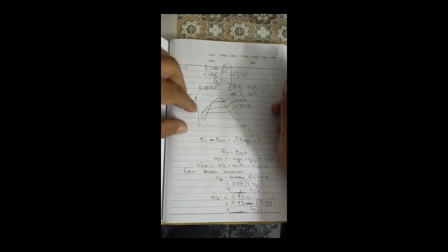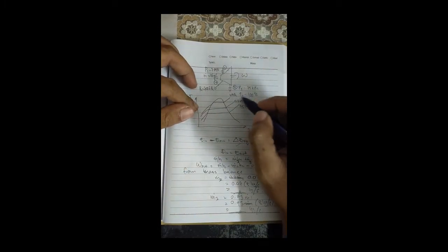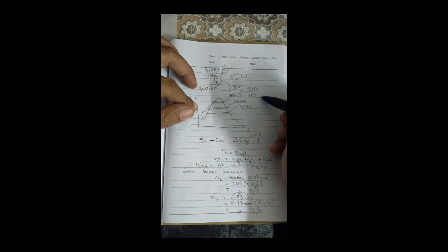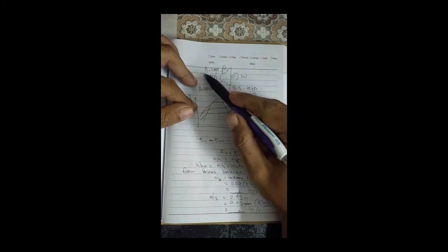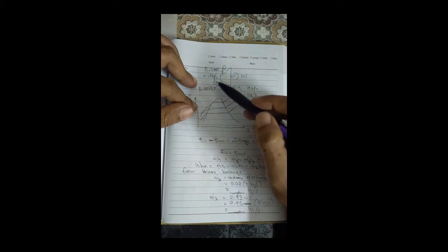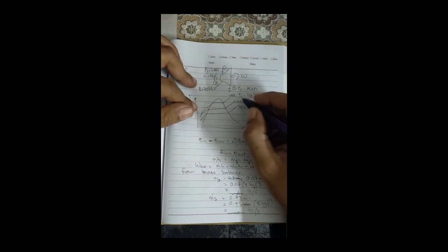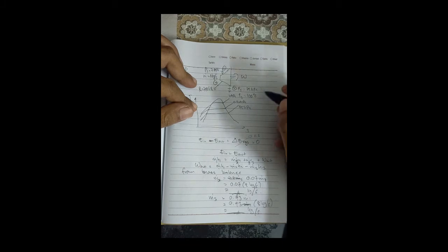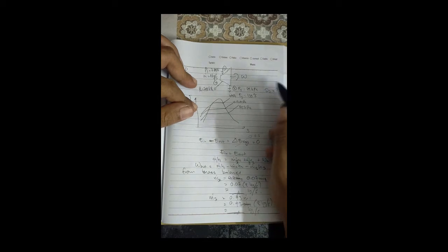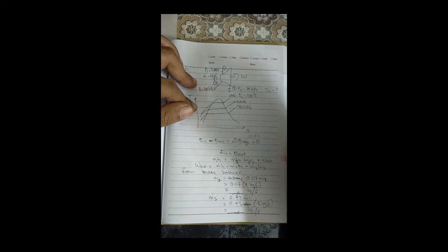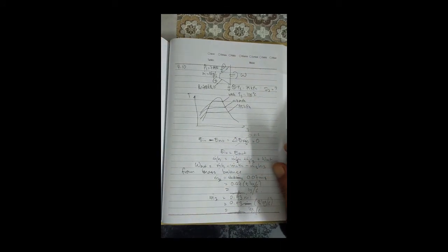Then what info do we have? The only fully given state is point 3, because it gives 2 properties, so we can refer to the tables. For point 1 and point 2, only one data is given, so we cannot determine their locations. From point 3, we can know S3. Since it's isentropic, it will be a straight line. So let's check the entropy at point 3.